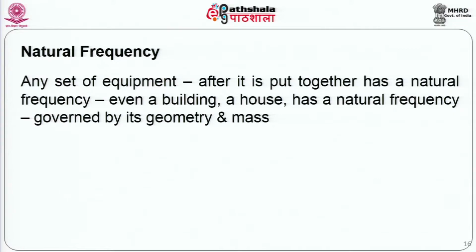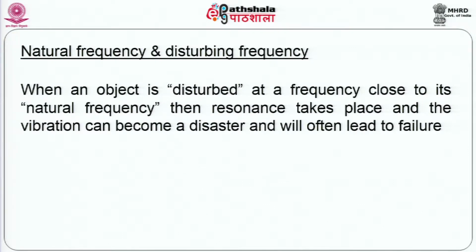So, basically what will be done is you try to put the natural frequency and the disturbing frequency far apart from one another. How do we do this? Like we saw in the earlier two examples, basically you play around with the natural frequency. As I said earlier, with the equipment one has very little choice except to buy the best. Having bought the best, we know that it has a certain amount of vibration. We want to make sure that it does not impact the comfort of the people who occupy the building, which is your topic of interest. So, at that point of time, you play around with the natural frequency of the structure.